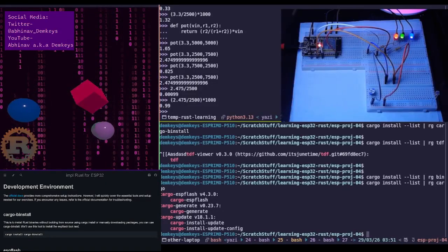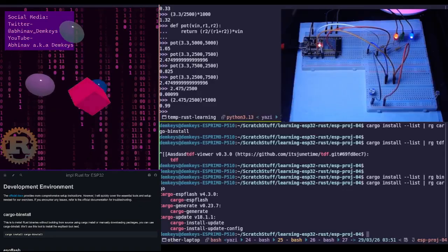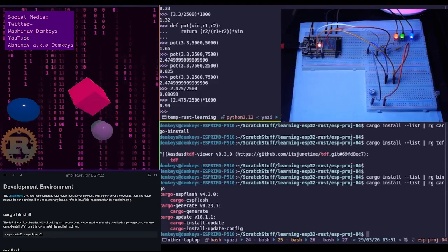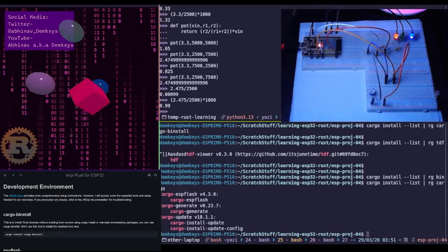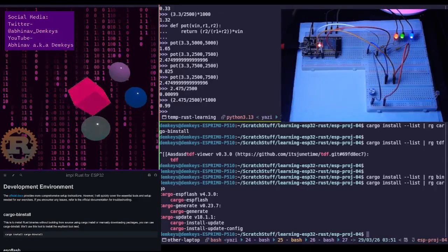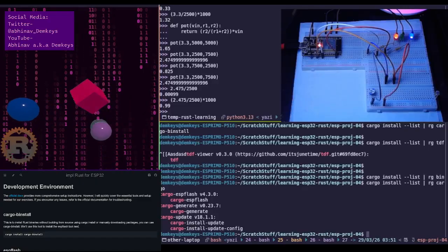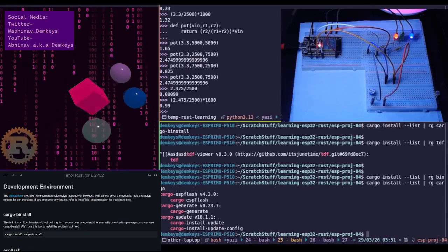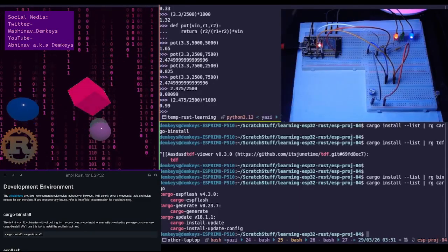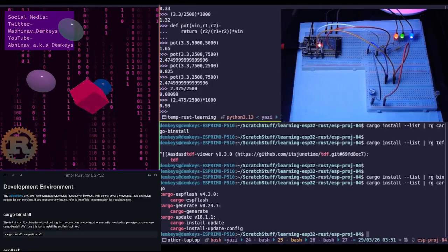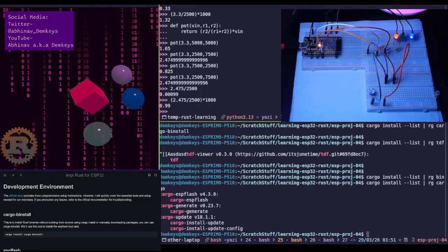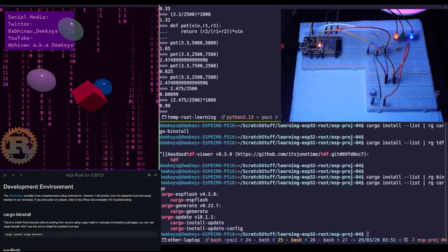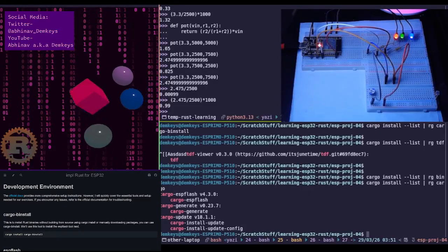Okay, so while a relay is the muscle that flips the switch, the ESP32's GPIO pins are relatively delicate and can't provide much current. The circuitry on a relay module acts as a protective high-performance interface between your low-power microcontroller and the high-power relay. Here's a breakdown of what those extra components are actually doing.